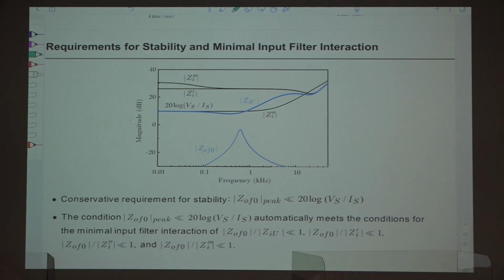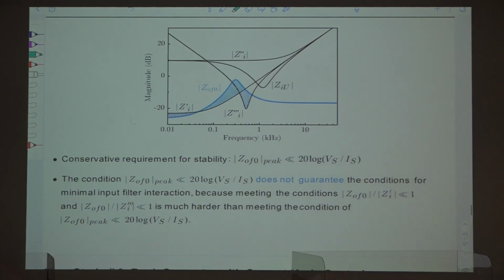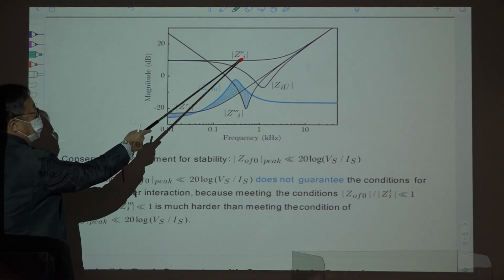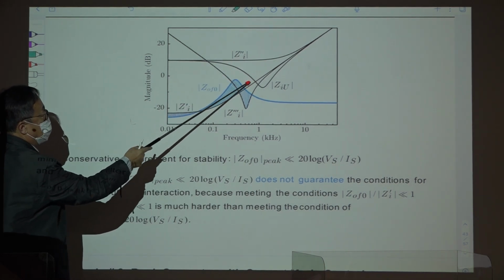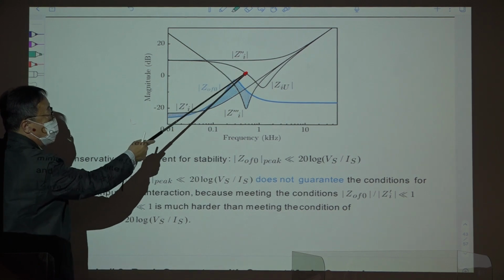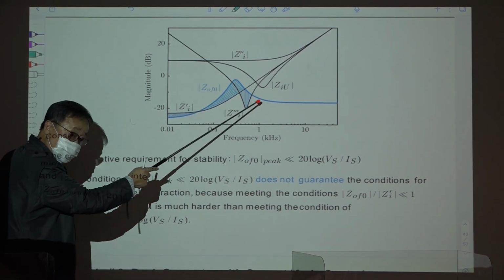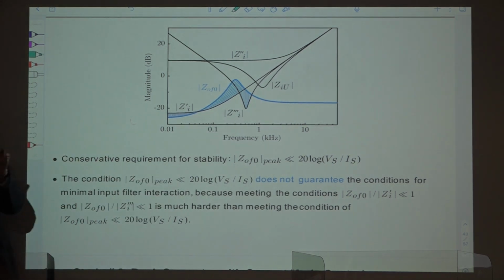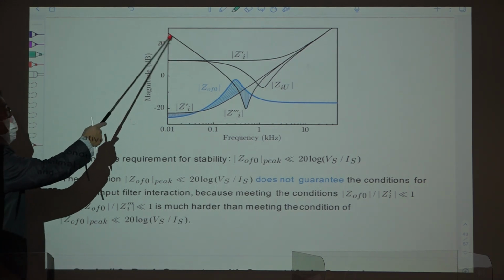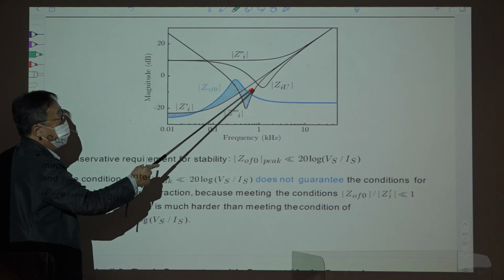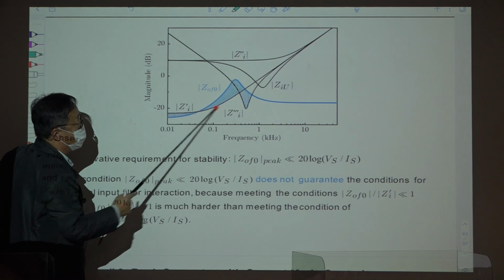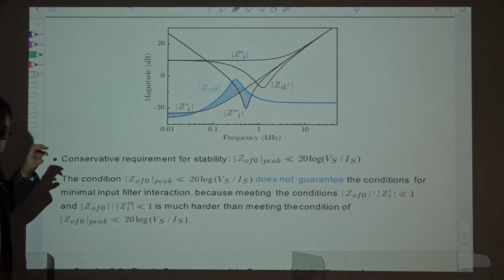So it compares with this case of voltage mode control. All right. So for voltage mode control, in this case, G_i double prime and G_iu are closed loop input impedances. So the voltage loop is closed, but this is the open loop input impedance. The only feedback loop, which is the voltage loop, is open. So the open loop characteristic is directly transferred to these characteristics. So we have this dipping here, another dipping here. This is the problem of voltage mode control.